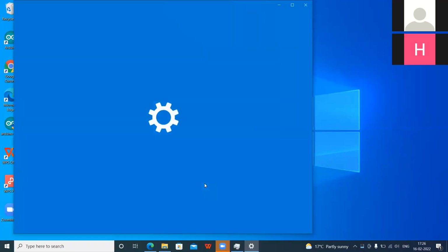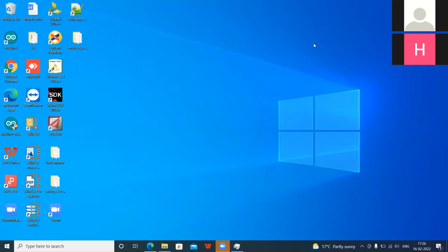You got the steps, right? So it will work. First we have to press on that simulation. I'll get the simulation window directly. Like if I click that option, I'll get those respective outputs. Yes. Okay, I'll check it. And also, if you run simulation, it will open simulation. But you have to run for 1 second. I showed you that, like adding the time scale and running, right? That you have to run for 1 second so that it will run entirely.